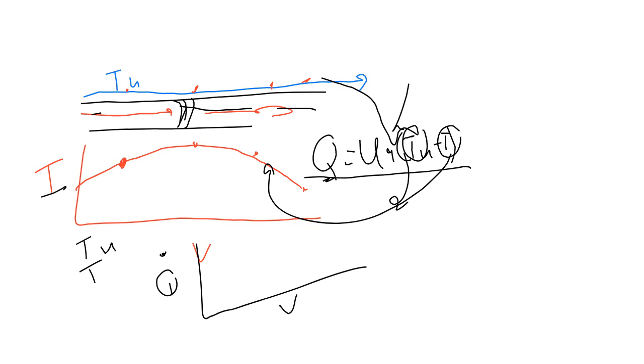The change in the utility temperature, no, because that will also depend on what the difference is between these two temperatures. So because the rate of heat transfer is not going to be constant, you may have a low rate and then a high rate, then it's going to go lower and so on. Because this rate is not constant, I will not necessarily get a constant slope for my utility temperature as well. Okay, cool. Right.